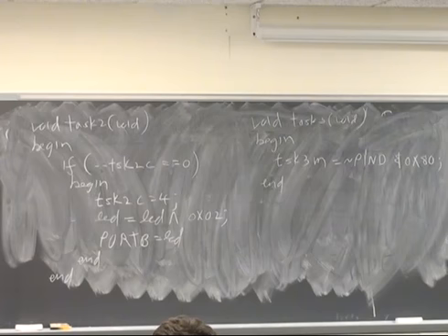So does that mean it's detecting the D8 push button? Is that the 7th push button? It's 0 based. Oh yeah. So the 7th push button, and the way we can detect on pin D is that because we wire that push button to Port D, right? That's correct. Yes. Okay, I see. D7 I think is pin 21. I think. Might be 22.